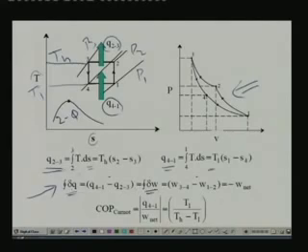So what are the different heat transfers during the cycle? We have heat transfer taking place only during 2 processes, process 2 to 3 and process 4 to 1, and Q41 is positive because you are supplying heat to the cycle, and Q2-3 is negative because heat is being rejected from the cycle. So we are following the sign convention.